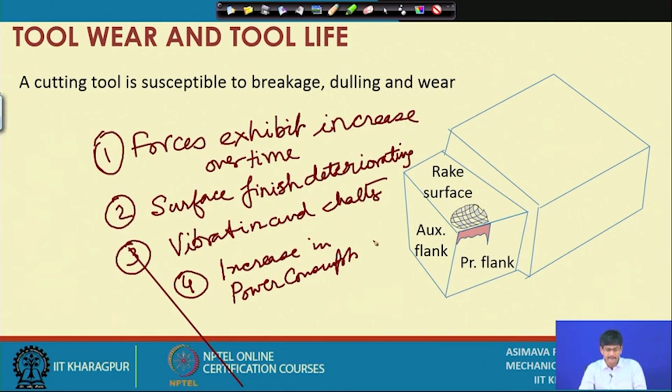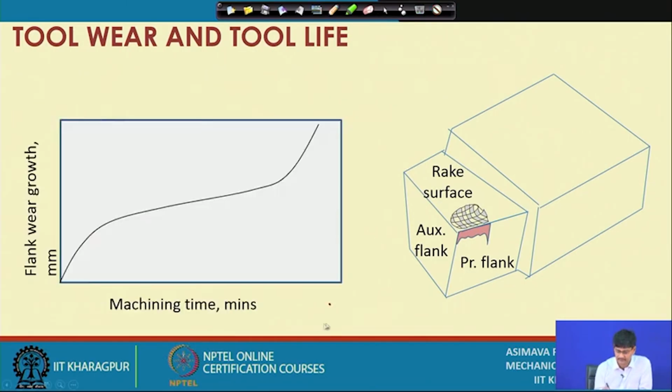There can be too much heat coming out from the color of the chips, etc. It can be found out. So, lots of indicators will be there showing that the tool has reached a particular amount of wear. So, let us have a look.